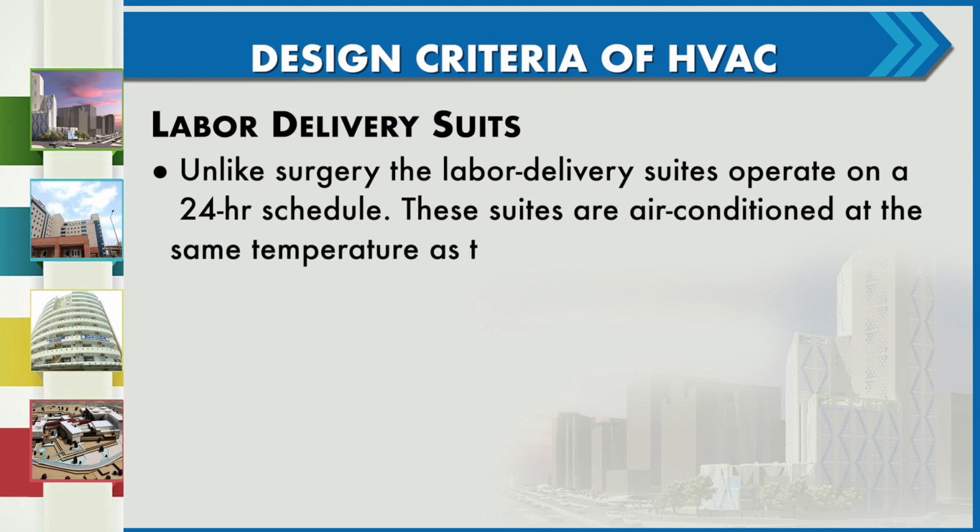Criteria of design of an HVAC in a labor delivery suite. Unlike surgery, the labor delivery suites operate on a 24-hour schedule. These suites are air conditioned at the same temperature as the operating rooms, which is usually 23 degrees centigrade.